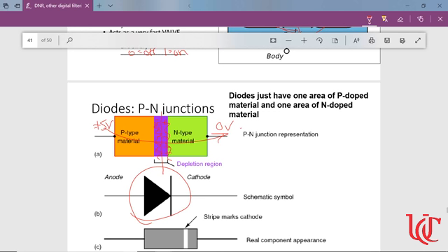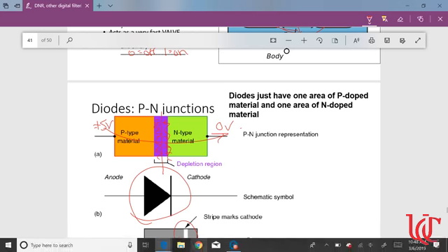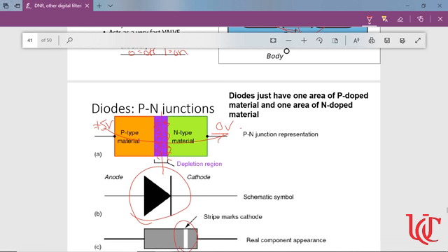They kind of look like little cylindrical rods for most of it. They're not as bulby shaped, and they only have one band instead of having 3 bands like the resistor. But that band is marking the direction for current to flow. So you want current to flow from positive to that band. Because that band is the cathode, or what should be attached to your negative charge. Your anode should be attached to your positive charge. Okay.